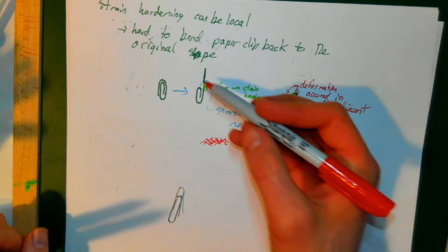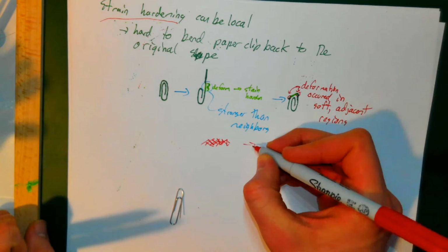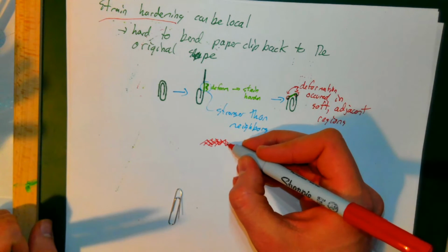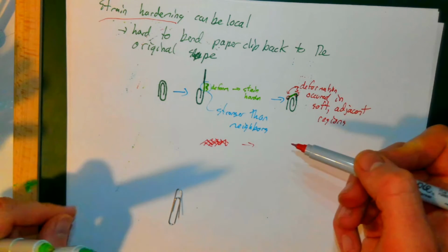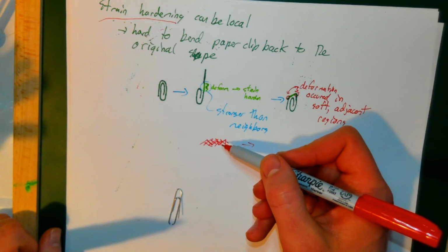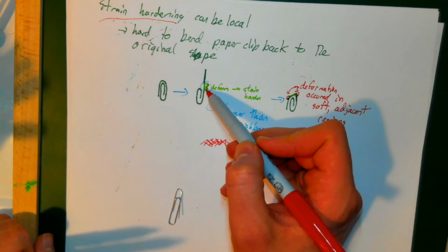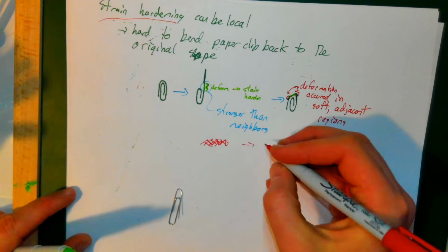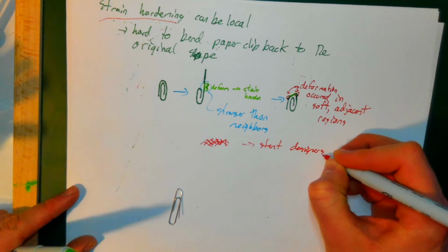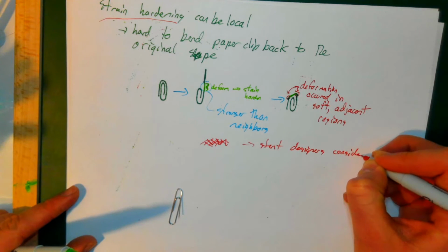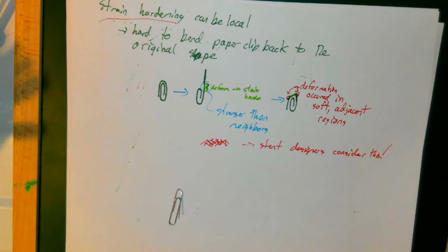Designers of stents need to be very careful about this strain hardening property, such that when you start to inflate the stent, the deformation occurs in the parts where you want it to, and not in other parts that have a lower yield stress than the parts that started deforming initially. So stent designers consider this, and that's something we need to be very careful of.